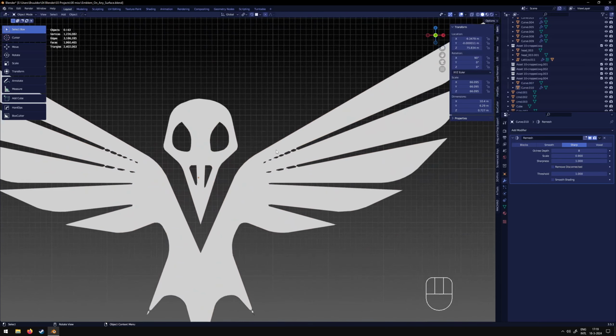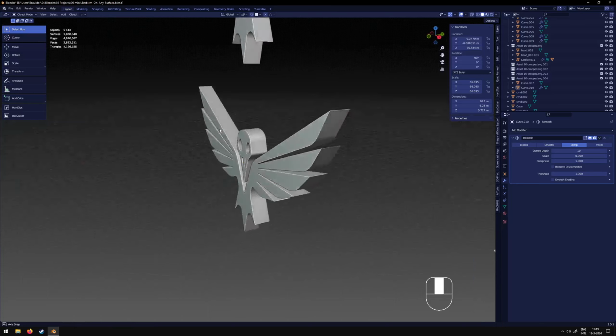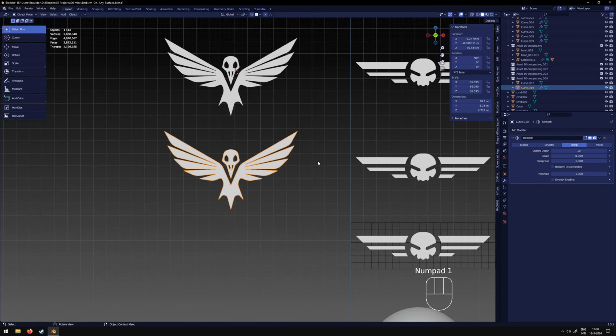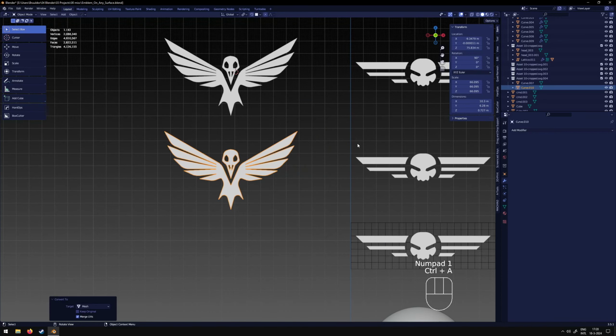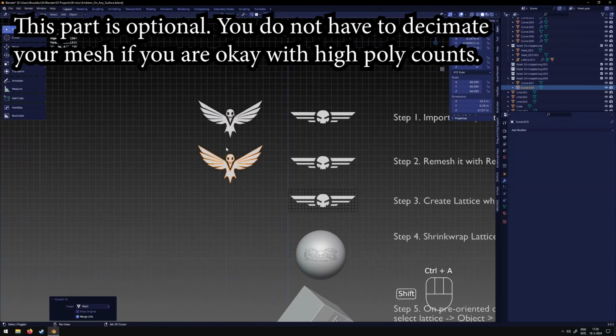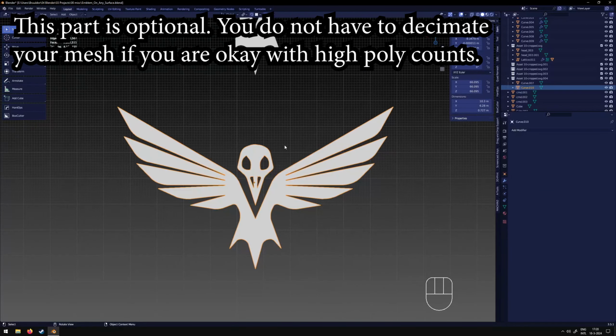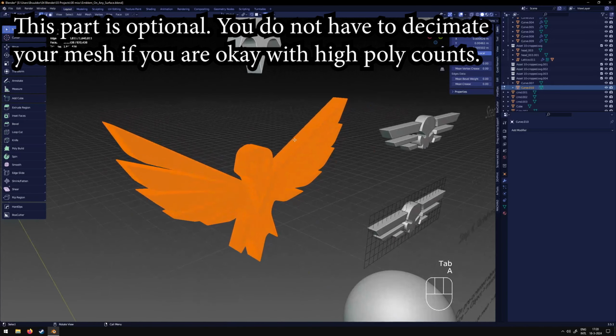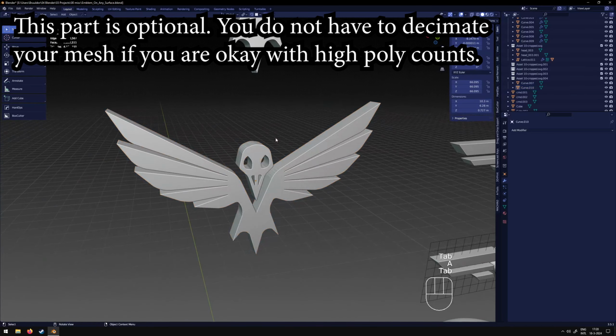Now, when I zoom into this, there's still some artifacting here that I don't like, so let's just up the geometry a little bit. And now that looks about right to me. And let's visual geometry to mesh again to apply the modifier. Now, this may take a little bit, depending on how strong your machine is. And now we have a very high density mesh. Now this may even be a little too high density for this, almost 2 million polygons.